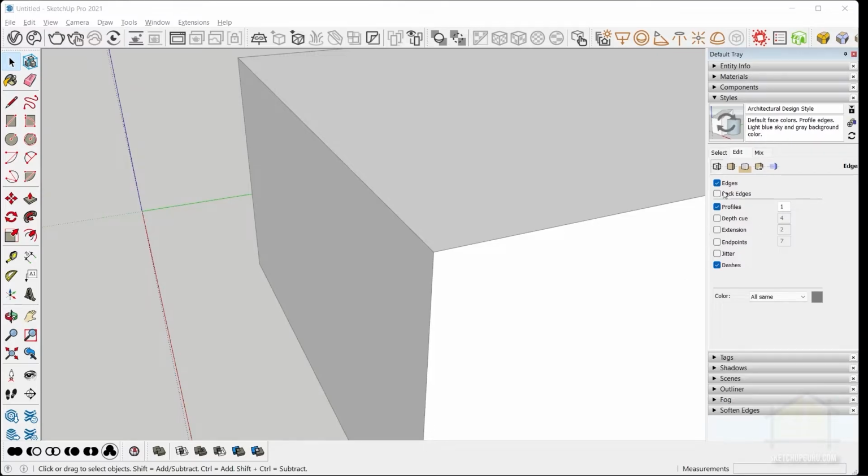Alright, next we can go to faces. So the front color is always white and the back color is blue. This helps to see which faces are reversed as well. It's always important to have your front color facing the camera, because that's where the material is going to be applied as well. And keeping the back color blue also helps us understand which faces are reversed in the model. For now, we can leave the settings as is, and we can change it later if required, and keep the style to display shaded with texture.